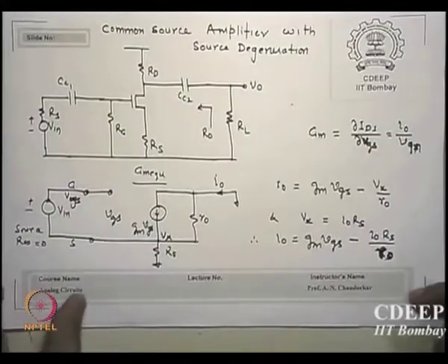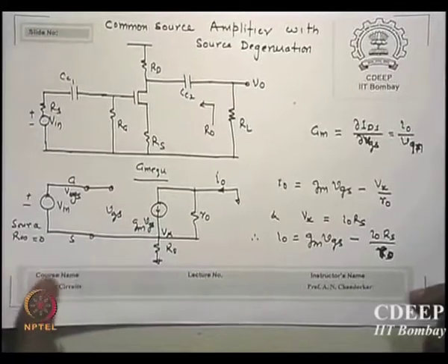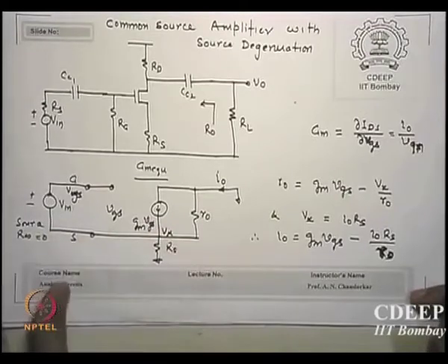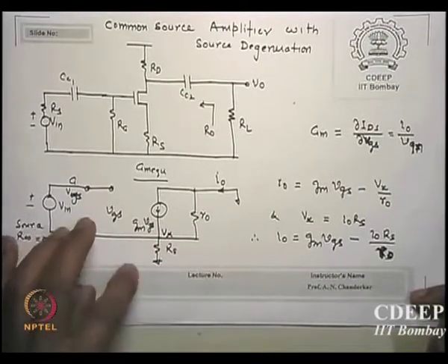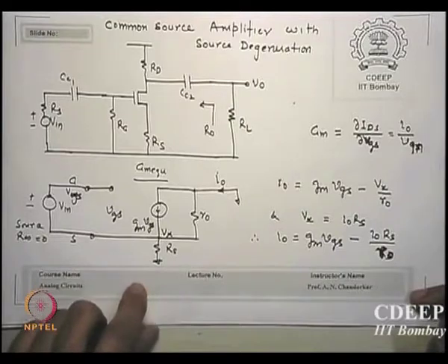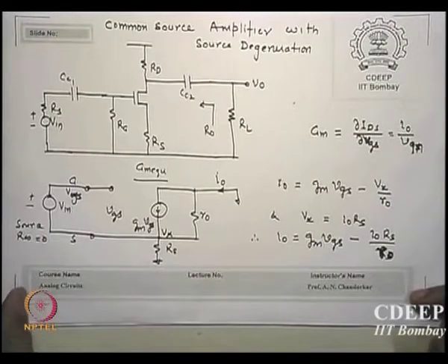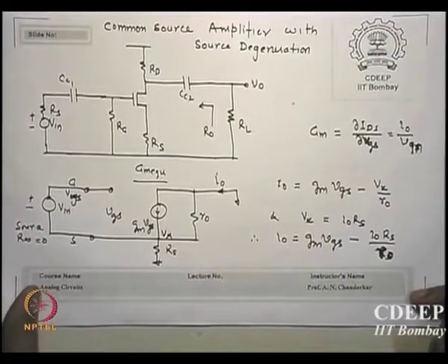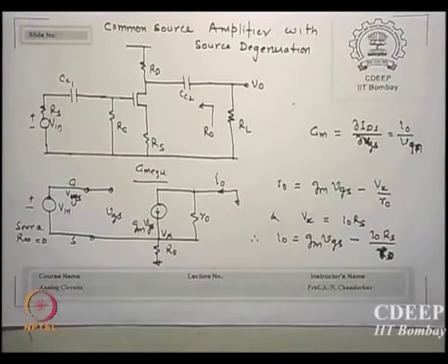I just want to show what we did last time. We actually put an equivalent circuit of that. All that is different now from the earlier common source is that there is a source resistance which is not bypassed by the capacitor, even for AC. Yesterday's question was, where is the biasing? That RG actually was RG1 parallel RG2 to the VDD,